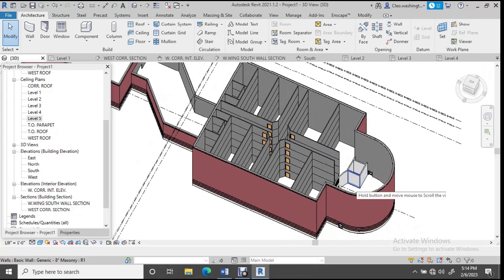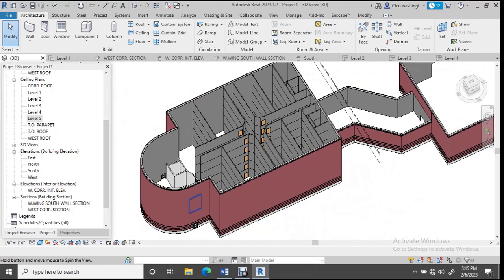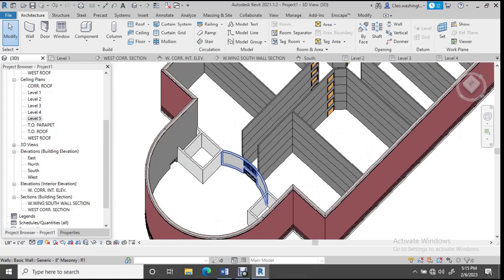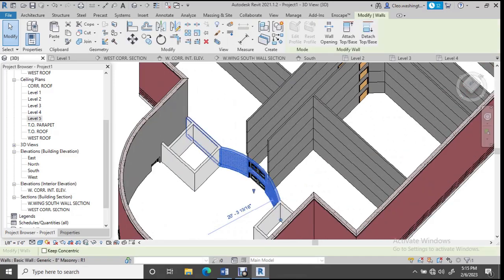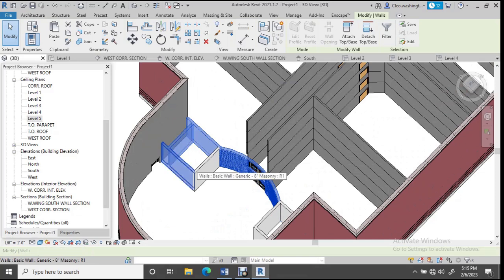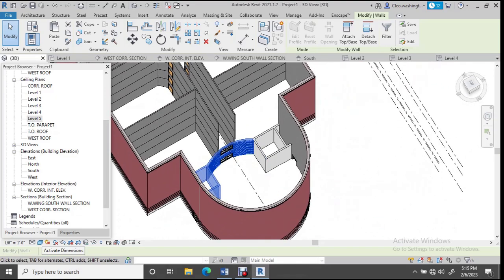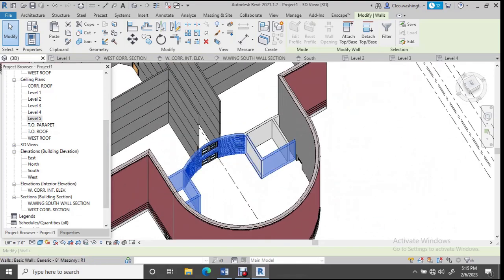And let's go ahead and extend the elevator shaft walls and the radius wall. We're going to extend that up, and I think we want to extend it to a roof, parapet roof. So go ahead and select them all, because we need these to show at every floor, right?